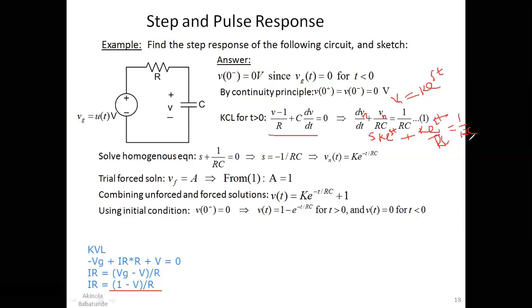By the way, when you're talking about the natural response, we're going to forget about this first constant. For the natural response, this is going to be equal to 0, not equal to 1 over RC, because 1 over RC is like our first constant term. So this would be equal to 0, and then the usual thing we do is factor out K exponential St, because it's common to everything. Then you have S plus 1 over RC, and everything will be equal to 0.